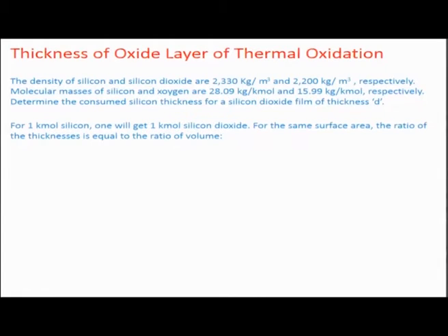So one has to realize something here, that when we talk about oxide layers, the oxide layer gets built on the surface at the behest of the silicon. So you have plain silicon which is now heated up and oxygen diffused into the silicon. So there is going to be some bulging and deformation of the film, and let us see how.